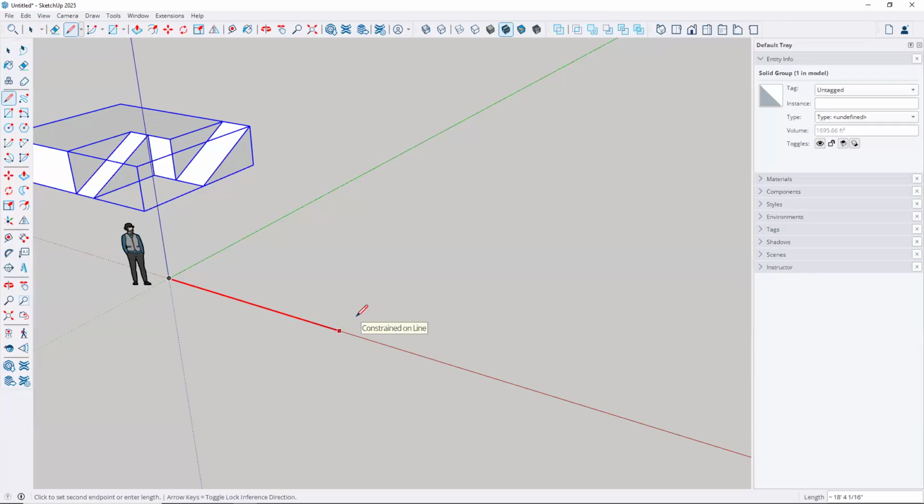So you can see we're going to draw a line that's 20 feet in length. So without touching your mouse, without moving it, leave it right where it is. Just simply type in 20, that gives you 20, and then the foot mark, which is the apostrophe. So length 20 feet, and then just enter. When you enter, you get that line, and it wants to continue drawing lines.